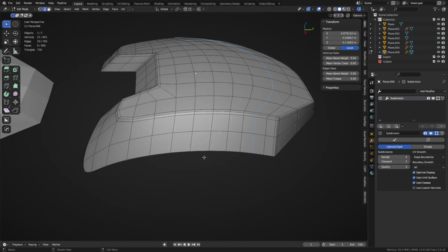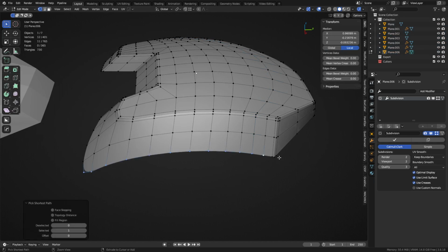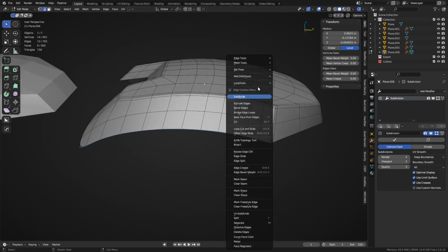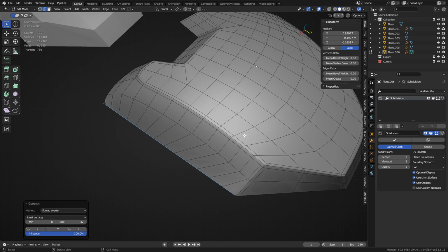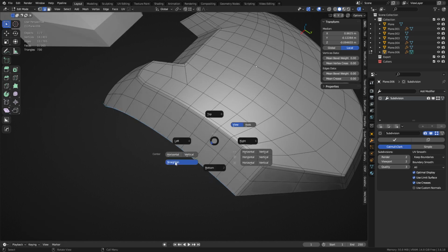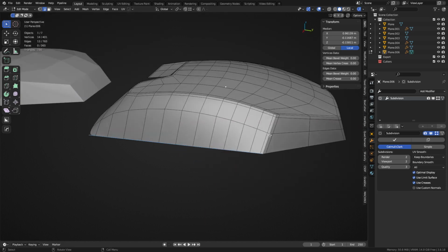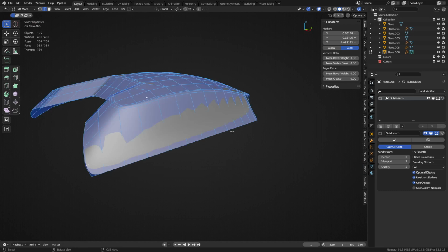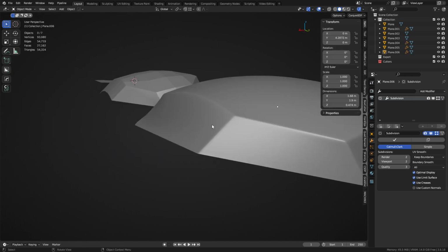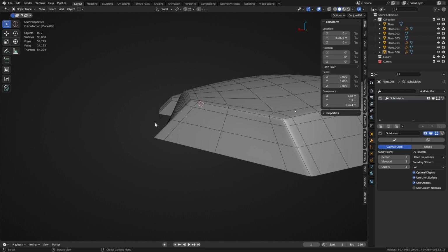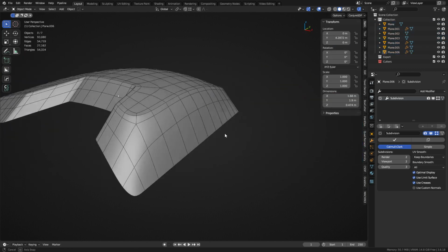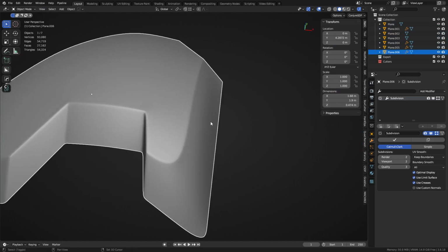So now use add-ons if you have them. You should be able to do something like this edge. You should be able to use loop tools and do something like G stretch perhaps, which just straightens it out, or machine tools, Alt A, straighten, one or the other. Not a big deal. Grab from there to there. You can do the same thing again. And you can start to knock out like a little curve there if you needed to. It's up to you. I like it rounded, so I'll leave that instead.